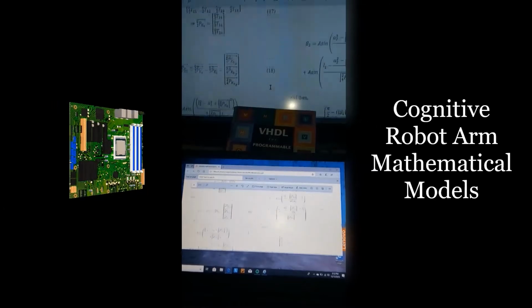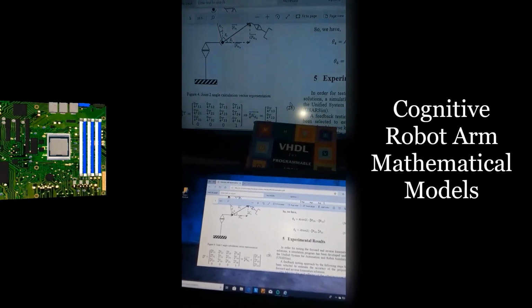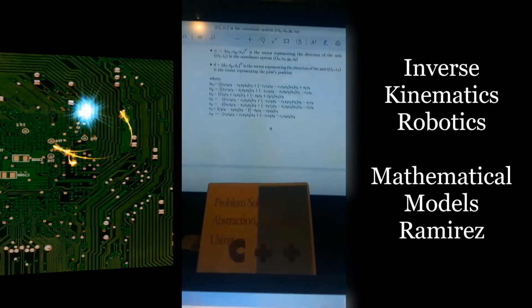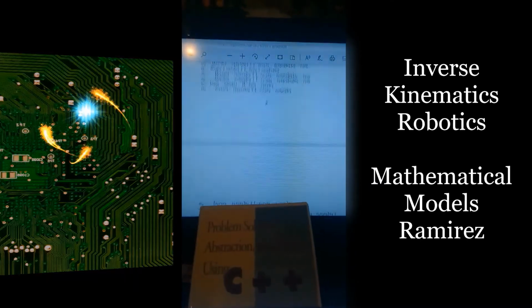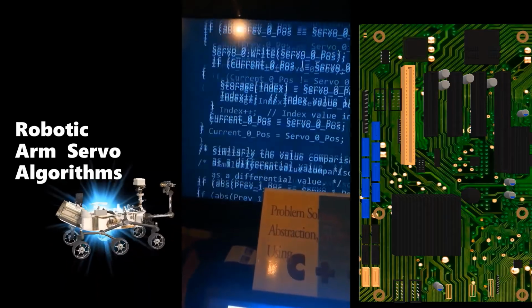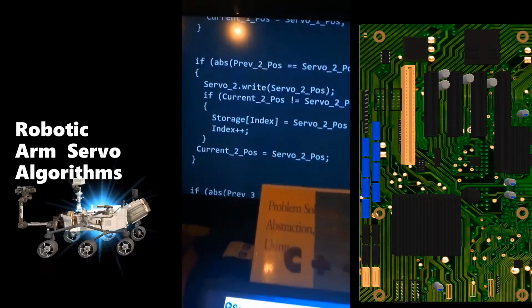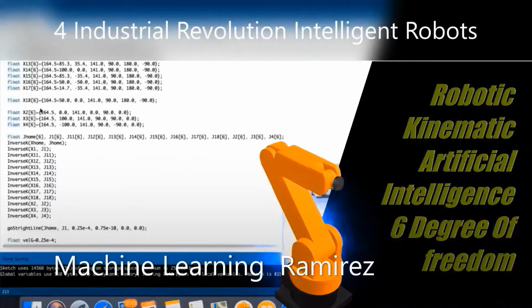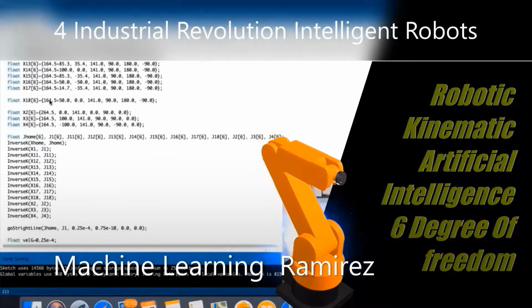The complexity of the inverse kinematic problem increases with the number of non-zero link parameters, and the geometric approach is used to solve the problem. The general idea of the geometric approach is to project the manipulator on the plane and solve the simple trigonometry problems.